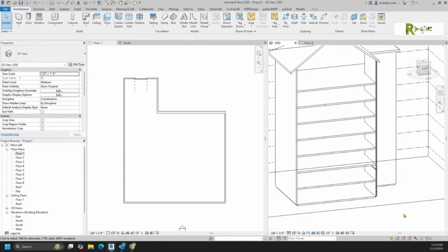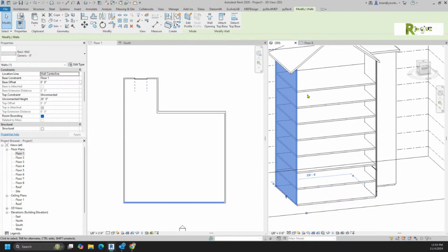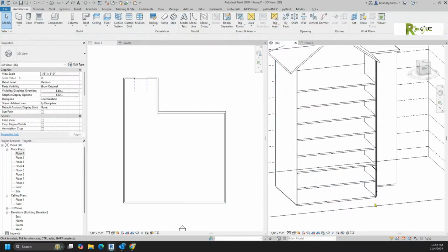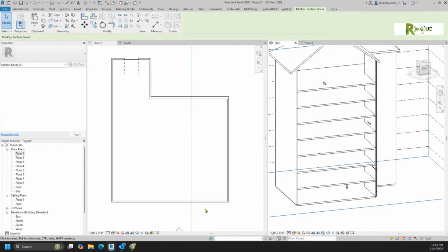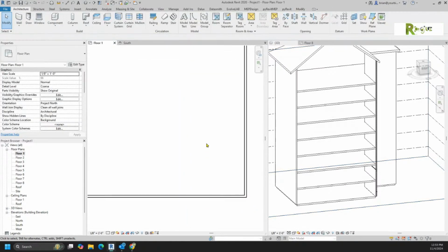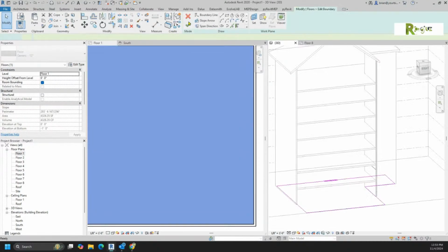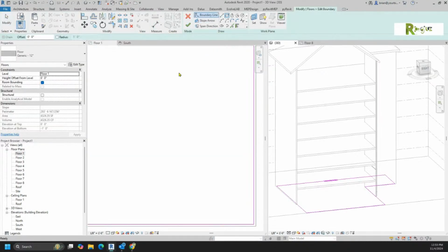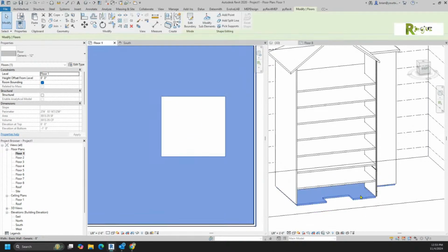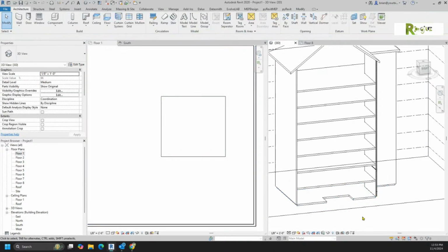Yeah, I got you. And then what happens is you end up moving this wall and you're like, I've got to go fix all those floors. To get that same relation, I would have to move the floor first. Correct. So Eric showed you a way that you could take this floor and say, edit the boundary. He said, if you just throw a nice little rectangle in here, it cuts a hole in the floor, right?